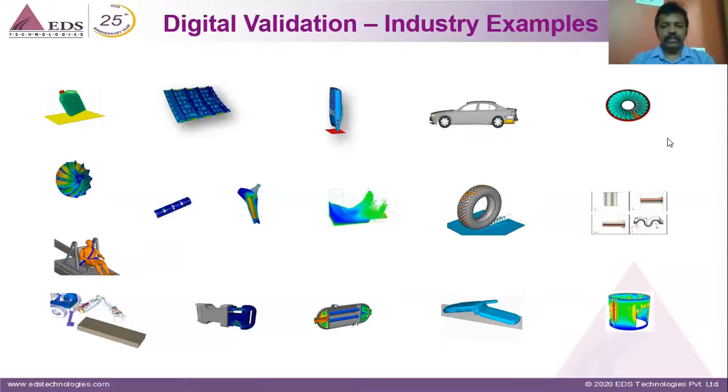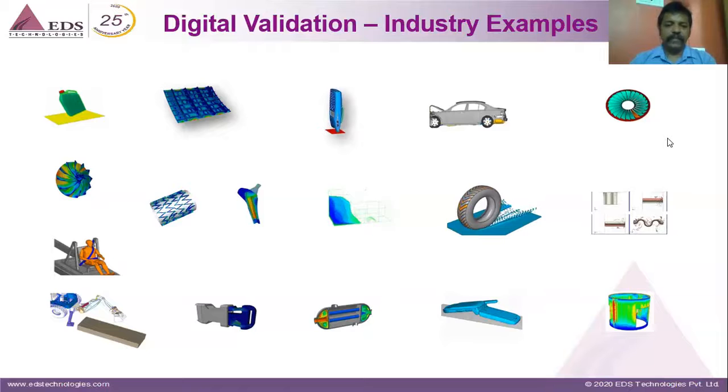So next comes sloshing analysis, which is again a CEL technology. Basically, in any aircraft, if you see the fuel which is stored under the wings, that has to be kept very carefully so that the aircraft remains balanced. Whenever the aircraft tries to roll or yaw or pitch, this fluid will create an extra inertia effect on the aircraft. So the energy which is produced because of sloshing has to be dissipated and taken care of. Even these kinds of things can be done.